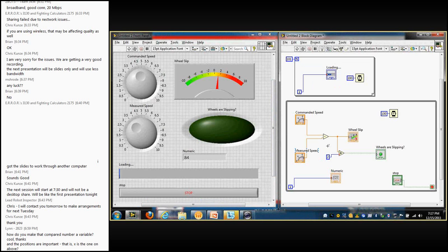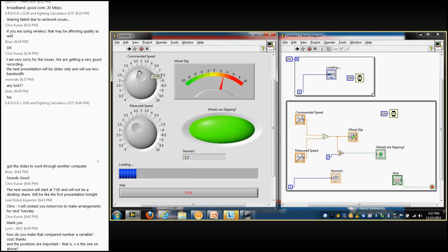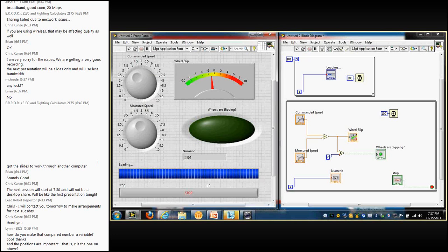If I hit run, these two loops will execute independently. What we'll see is that I can do my math up here, and my progress bar is loading at the bottom there. Once this gets to 101 iterations, which displays 100, that will stop at this point. This loop is no longer running, but my while loop continues to run because it runs until a condition is met. So I can hit stop there. But one of the nice things about LabVIEW is when you want to run two things in parallel, all you do is just put a second loop out.